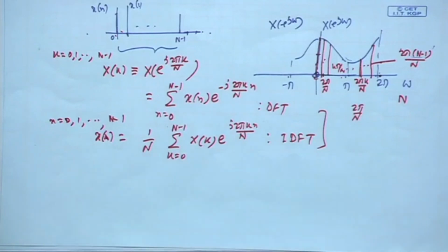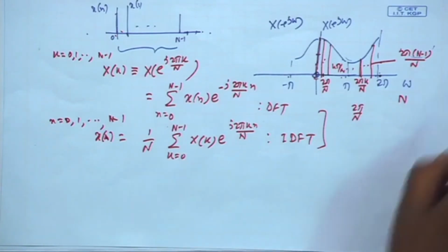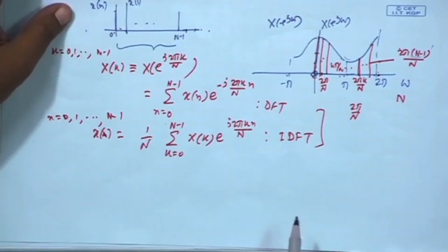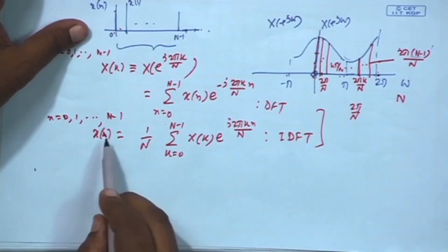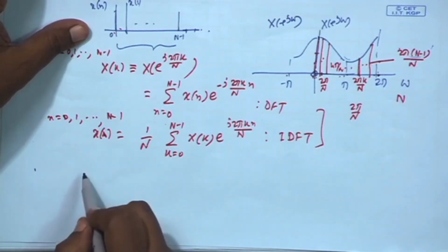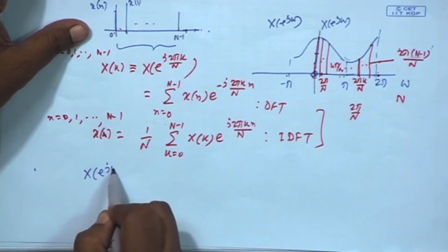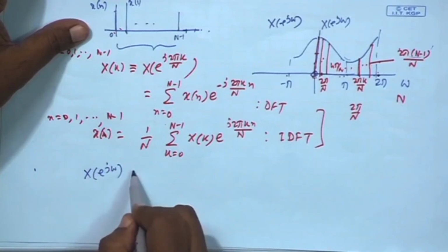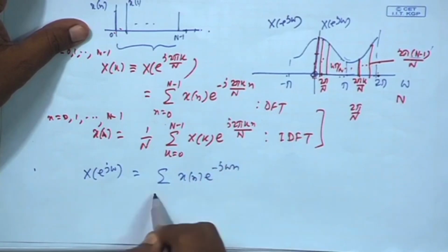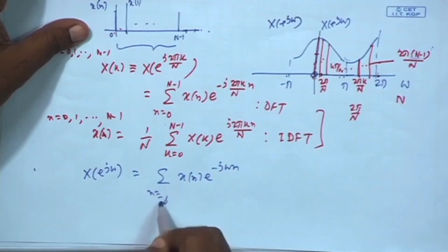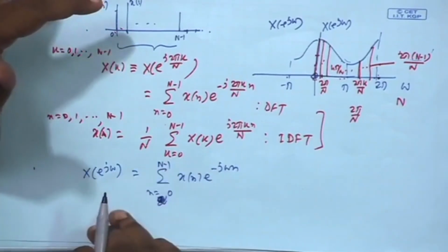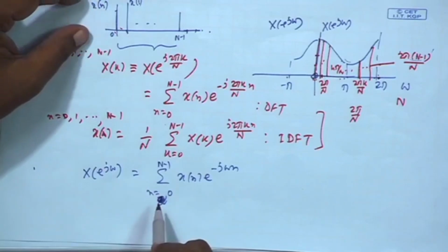All right. Now, there are several properties which will follow, which we will discuss. Number 1, if I take this x[n], from x[n] I can get back the full DTFT by this formula, n equal to 0 to N minus 1. Given any x[n], I know the full DTFT.